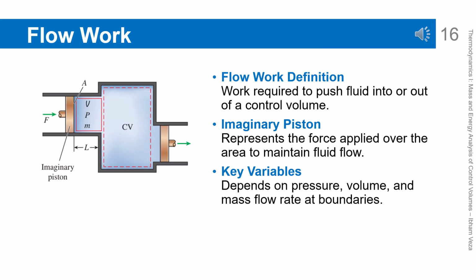Flow work concept. Flow work is the work required to push fluid into or out of a control volume. An imaginary piston concept is used to visualize the force due to pressure. The magnitude of this work depends on the pressure and the fluid volume being moved. Flow work is always associated with open systems. This concept becomes the basis for introducing enthalpy.